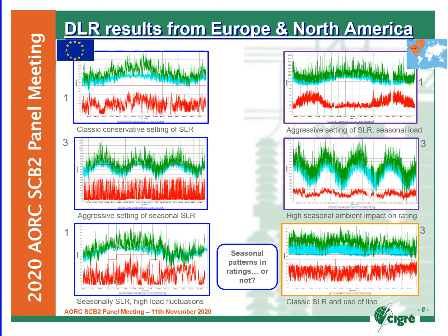The seasons can also affect the line loading, like the top right system, where there are high peaks in summer, and the middle right, where there are high peaks in winter. Perhaps you would think that dynamic line rating is useful only in areas where winter load peaks coincide with cooler conditions, releasing the capacity. But you see that customers find dynamic line rating useful also in cases where the high load situations lead to a tight operational situation, to make visible and therefore control the risk.